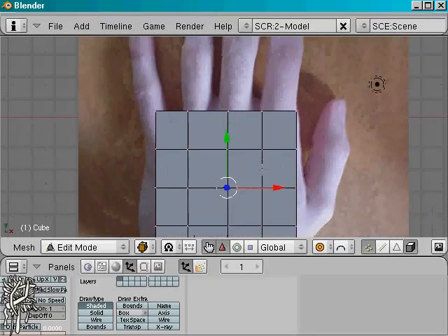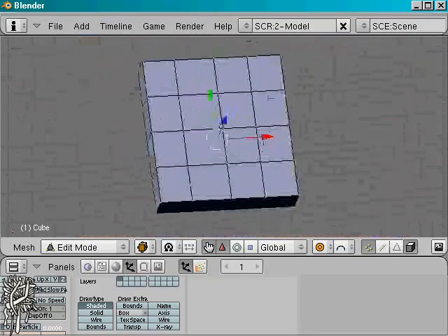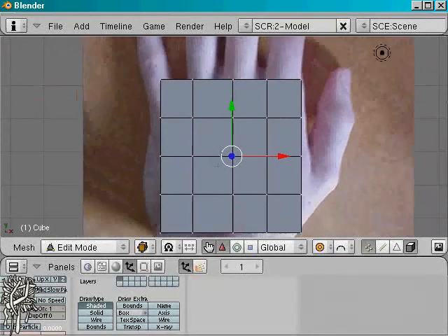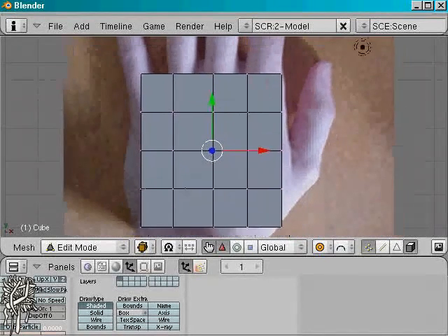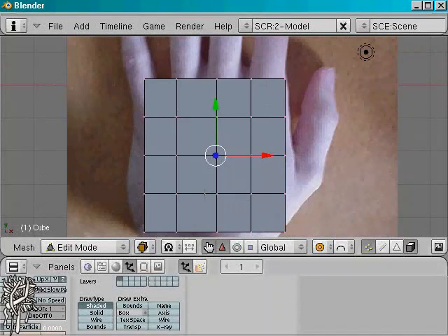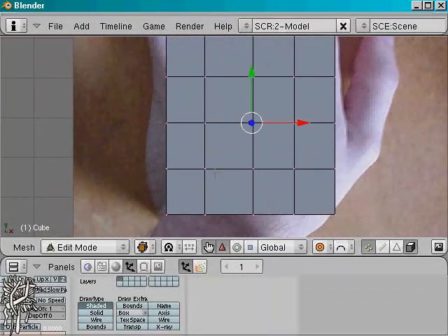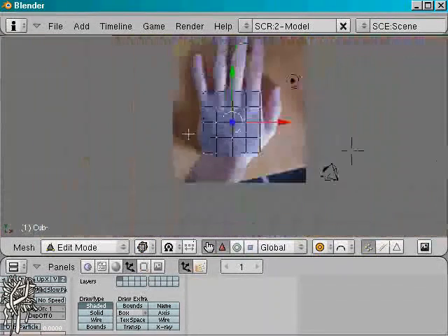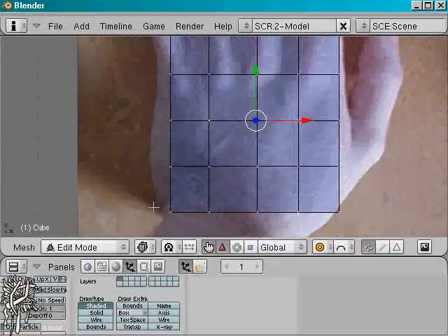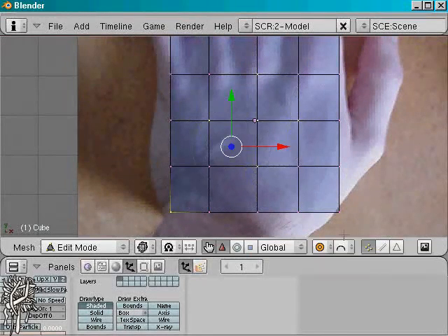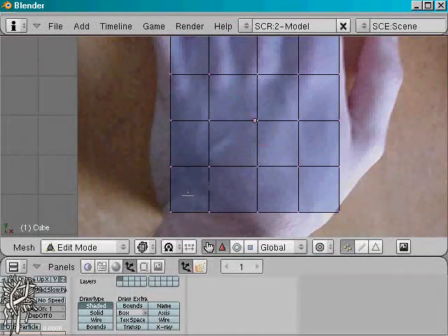So we've got a primitive cube. I've made a few cuts here just to make it a bit easier to model with. This should be fairly simple for you. Use the Ctrl-R loop cut tool. Okay, let's start off with just blocking out the basic shape. So Z to go into wireframe mode so we can see what we're doing, and box select, and whoops, got soft selection on there. I don't want that on at all.